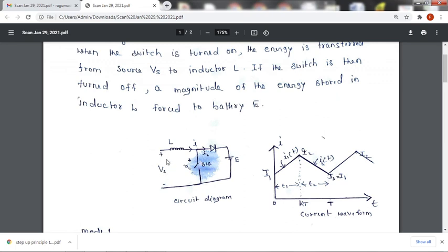So here we need to think that there is a motor, and that motor is acting like a generator. That energy we are initially giving to an inductor by closing the switch, and later we will open it. Then the EMF induced in the inductor reverses sign, this side minus and this side plus, and these two energies are added together and given to the battery. So if this is your electric vehicle battery, I can charge it during regenerative braking. This is widely used in such applications. Thank you.